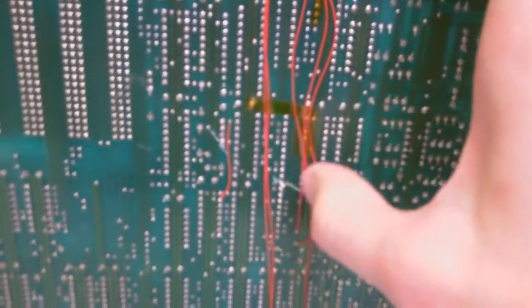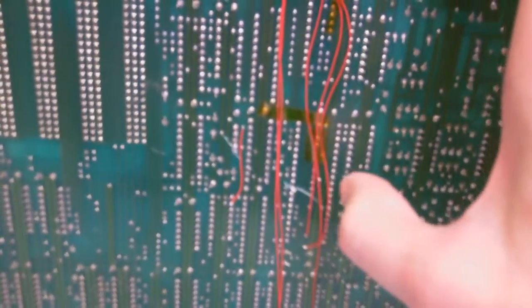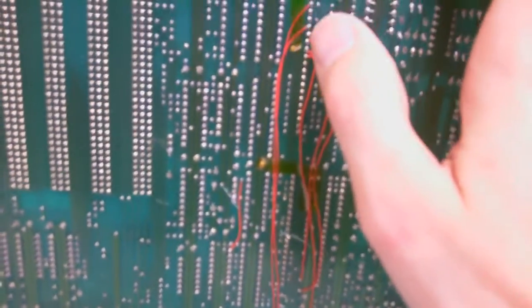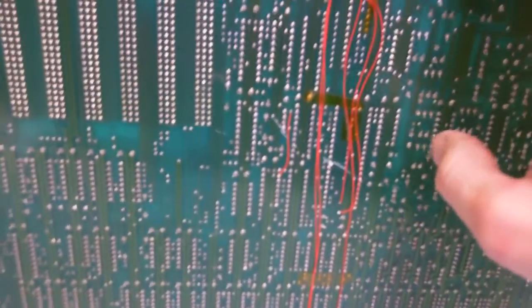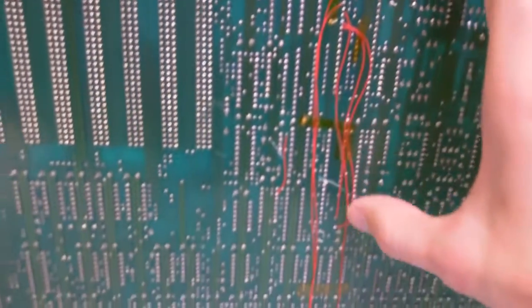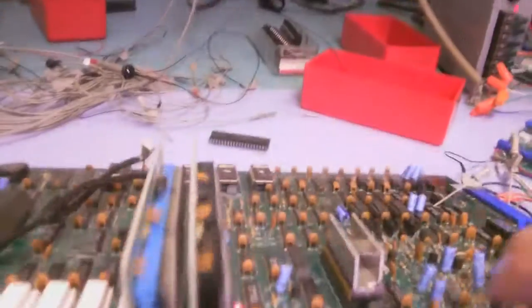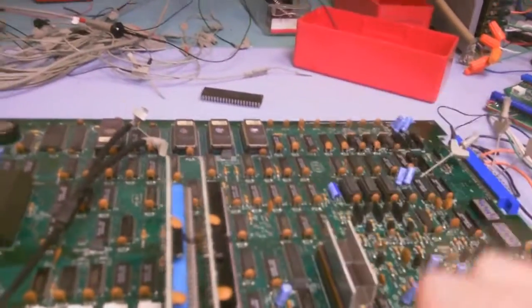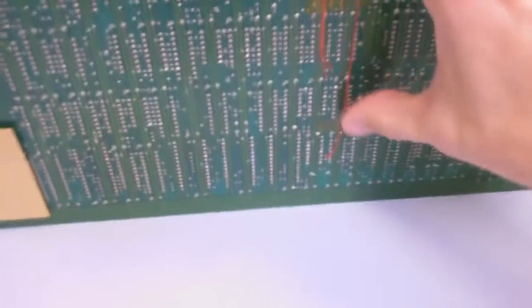I don't know if you can see this, but right there, it looked like the board got scratched, and there's a mess of traces right here that probably got affected due to that, and so somebody tried to correct that by running traces all the way up and down the board. However, just by eyeballing it, I can see that 32 is right here, and rather than end up at 4L, which is right around this area here, it just keeps going all the way down and ends up getting tied to some junk down here.